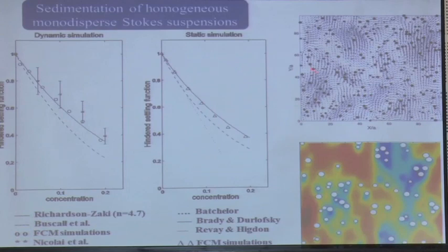And here we use that technique. So this is the kind of information that you can get here. You see all the black dots or the white dots are actually particles which have been fully meshed. So the mesh is, let's say, 10 or 20 times smaller than the diameter of the particle. And then we have full access to the fluid. You see the fluid. Actually, for these arrows, I just took 1/10 because there are too many to see. But we have full access to the fluid in between all the particles here.